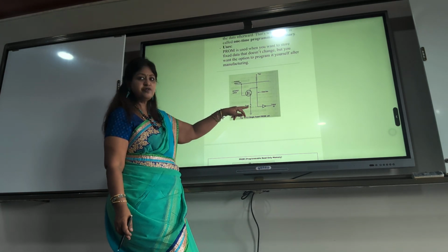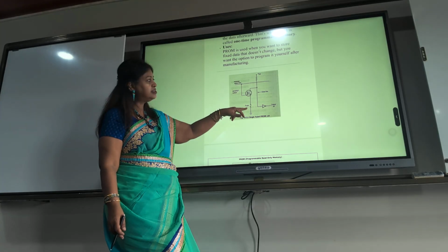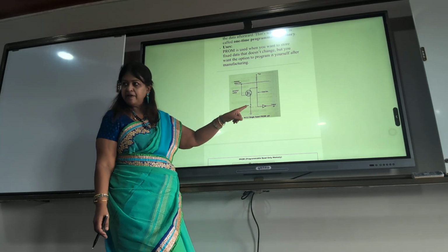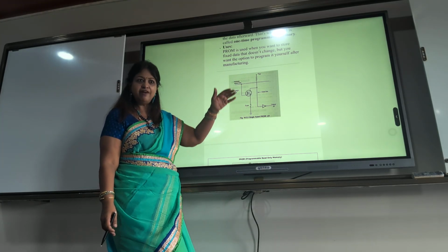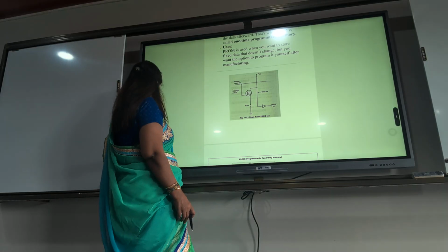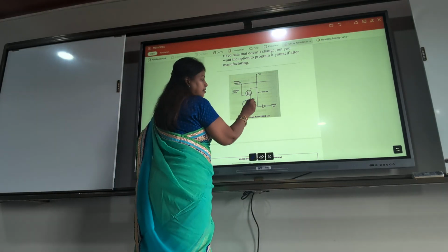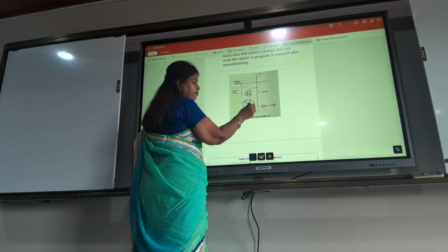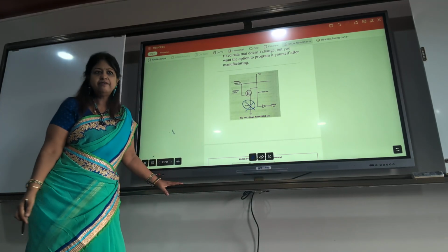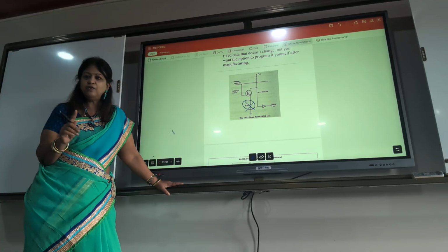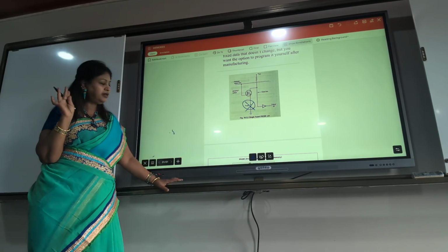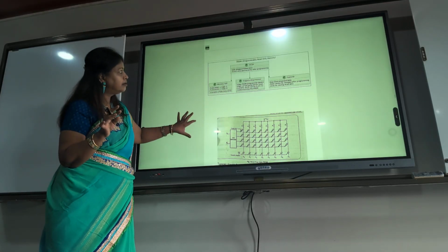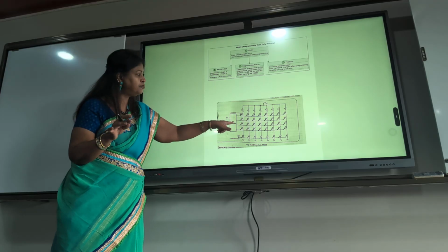So here you have a fuse, right? This is one PROM cell. Like this you will have a number of cells. This is the fuse. Initially they are connected and given to you. When you don't want a bit, you will blow that fuse. How many times can you do that? Only once. So this is how the fuses work.